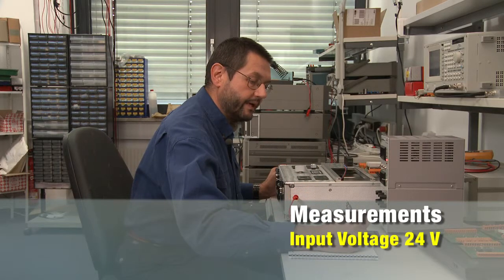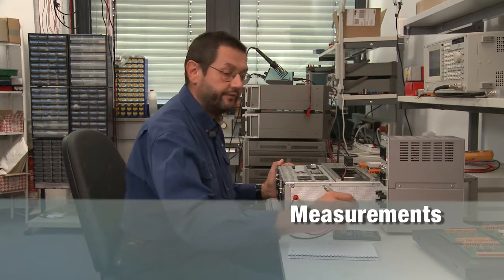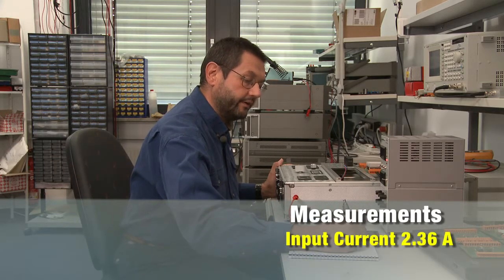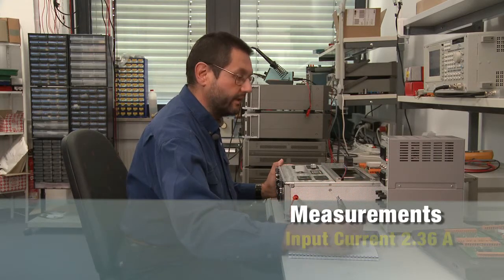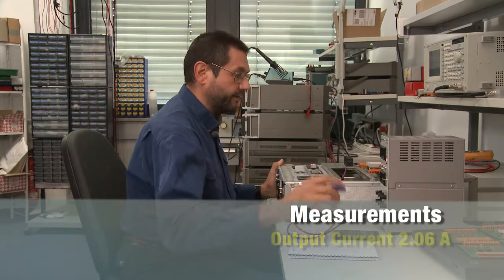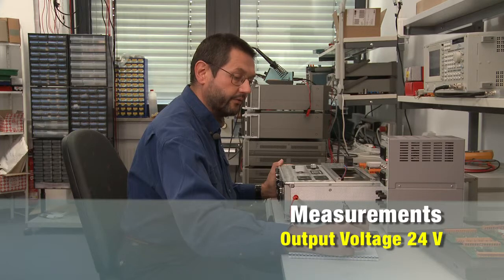It's very important to make a precise reading of the displays in order to have an accurate calculation of the efficiency. The input current is 2.36 amp because we have set an output current on our load of 2.06 amp, and the output voltage of the module, it is a 24 volt output, and we read exactly 24 volt.